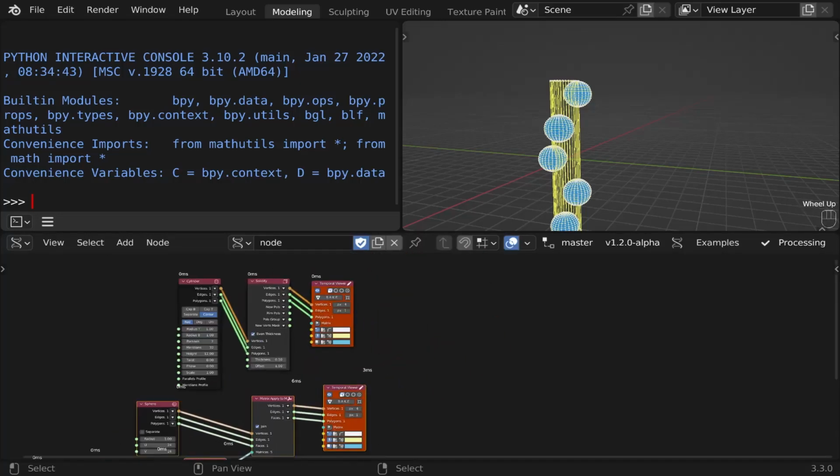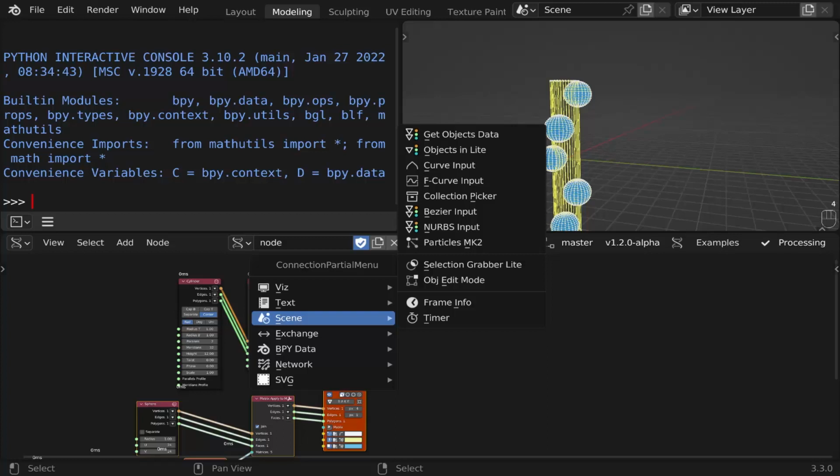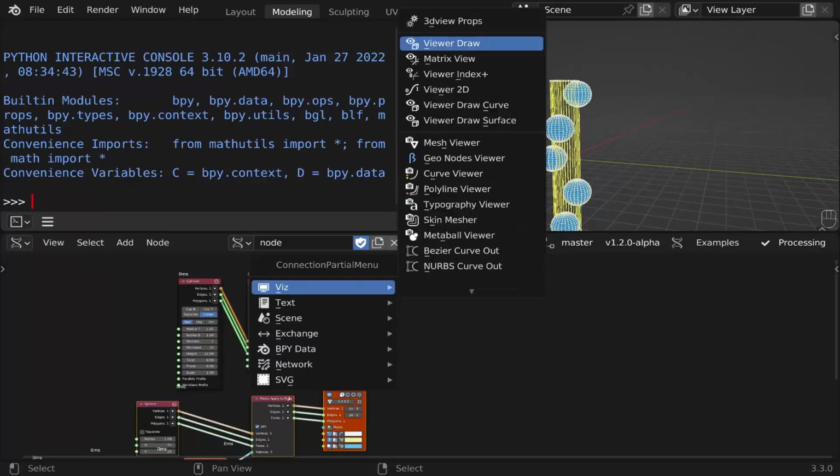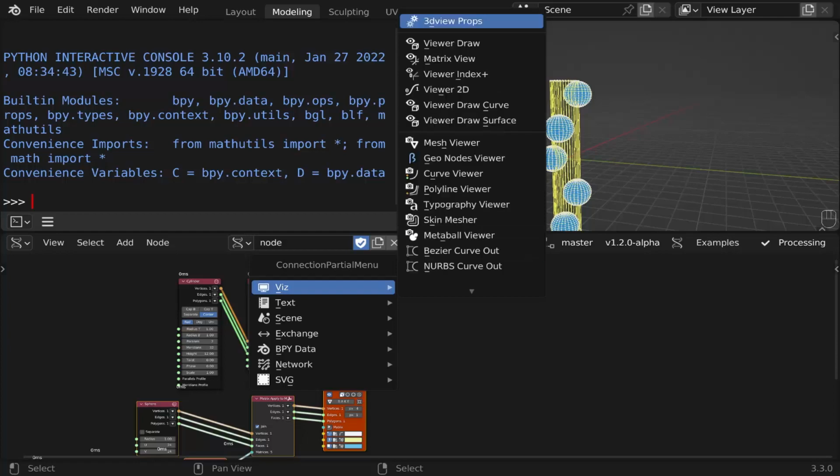By far the best way to implement the Sverchok Boolean function is with the help of the Blender Boolean modifier. So, we need to export these two geometries as Blender objects.